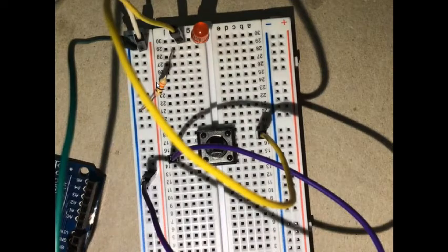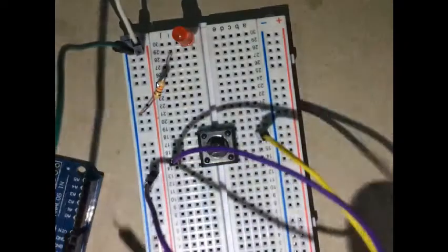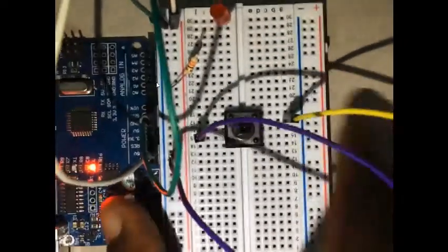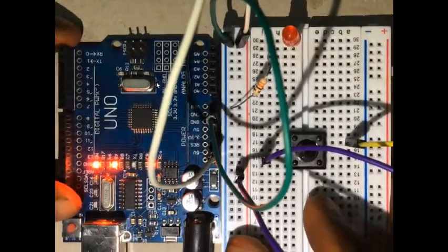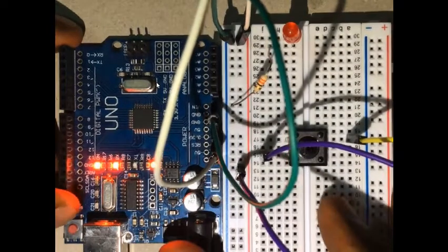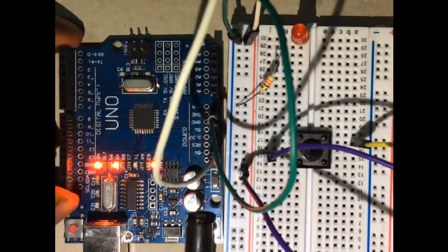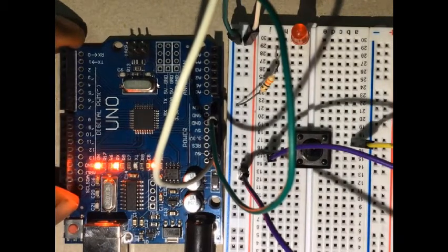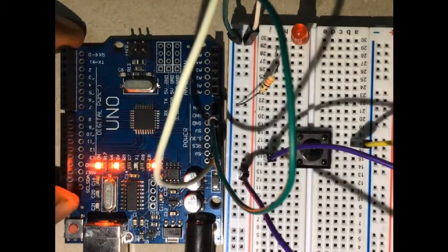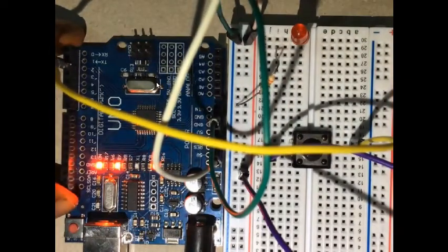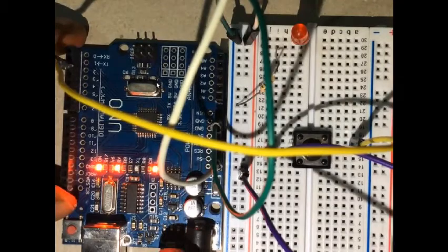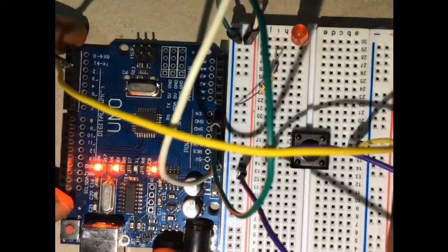When you are connecting a button to a digital pin, this is the Arduino. Now we are not going to program it in this video because I have not even introduced what a button is, and I've not even introduced how you can program a button with the Arduino. But I just want to quickly mention this because I may not mention it in the next video. When you are working with a button, like when you want to read in digital input from it, let me connect it to pin 2 now. That is connected to pin 2. So when you want to read digital input from a button, you have to connect a resistor to it.